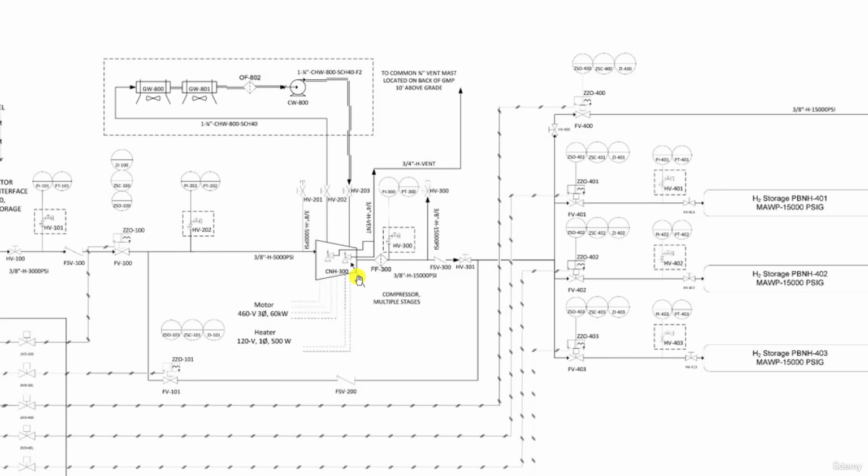And you are able to figure this out by simply examining the symbols on the P&ID. This is why P&IDs are so powerful. These two pressure relief valves have a common discharge line. In our case here, the excess hydrogen gas is routed to a safe location 10 feet above the ground.